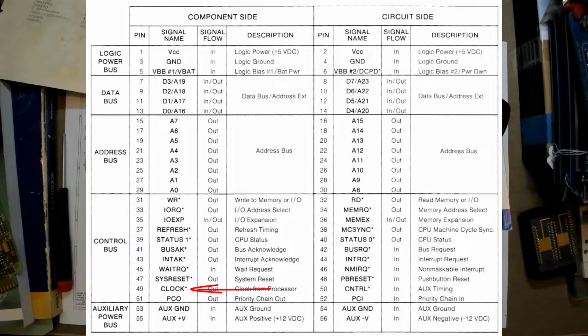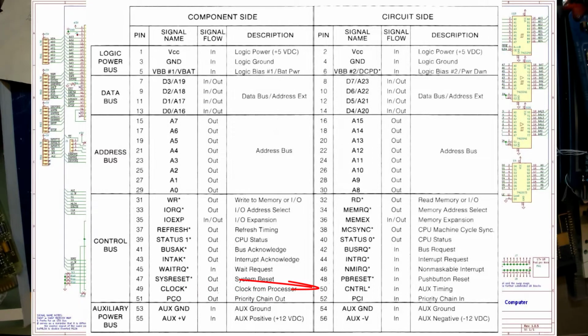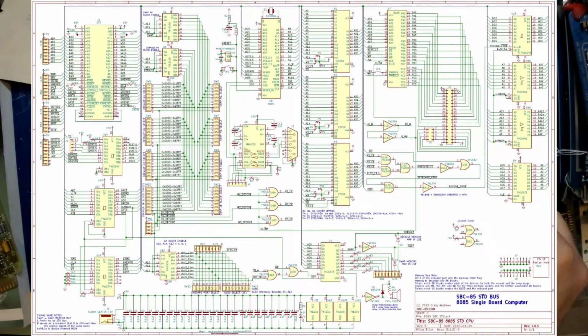Pin 49 is the bus clock, which is just inverted and it's continuously driven onto the bus, meaning it's not tri-stated with the hold acknowledge signal. So pin 49, the clock, is always available. And pin 50, as I already mentioned, is the auxiliary clock, which is just brought out to a test point. So that's it for the control lines.